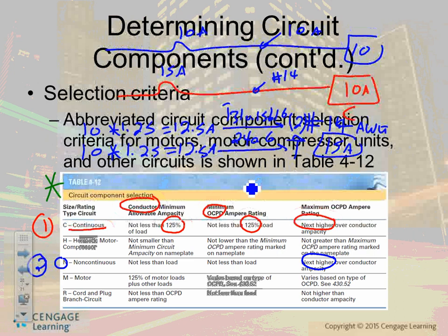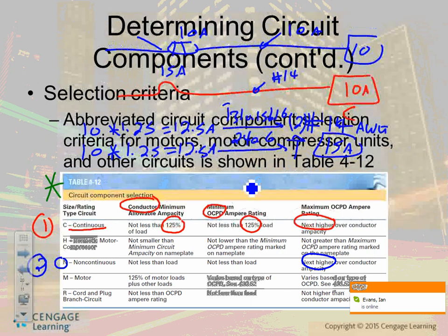Look at the bottom, guys, in that 240.6. I thought there was an exception at the back for additional ratings, 10 amp fuse, 1.6. Thank you. There are 10 amp fuses, way at the bottom. So, look what happened. Now, you don't do this one typically. At the bottom, here's my fuse. And that'll be a what? A 10 amp. If I want to fuse it, that'll be a 10 amp.